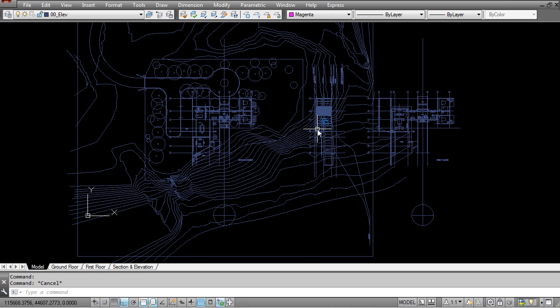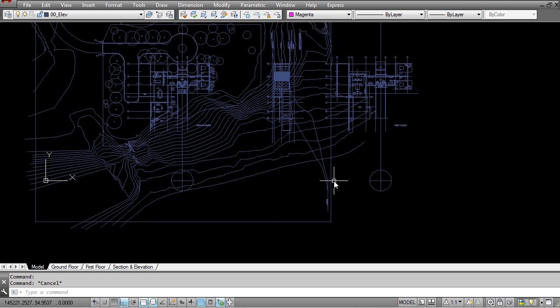The last thing I wanted to mention before I finish this lesson is that you want to make sure in the AutoCAD stage that you know where your 0 point, or at least your datum point, is for your model. When we import it, the elevations and sections are going to be turned by 90 degrees so that they are upright in 3D space. You want them to be projections of the sides from whichever point they are being drawn from. So you need to know which rotation point you're going to be using, and you want to make sure that it is clearly defined.